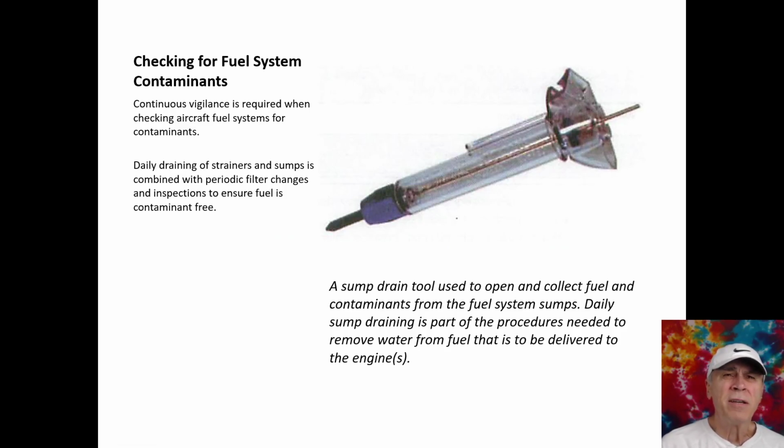If you're going to be checking for fuel system contaminants, it requires continuous vigilance. Certainly your fuelers are going to be particularly aware of that. Daily draining of strainers and sumps is combined with periodic filter changes and inspections to ensure the fuel is contaminant free. Here's an example of a sump drain tool.